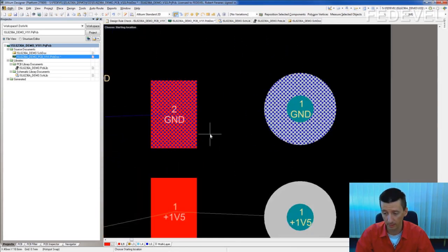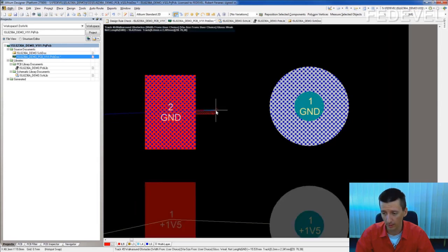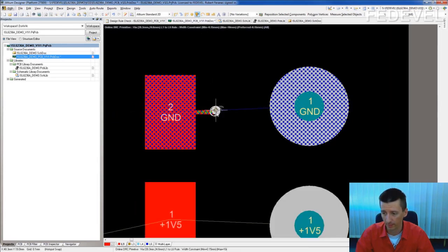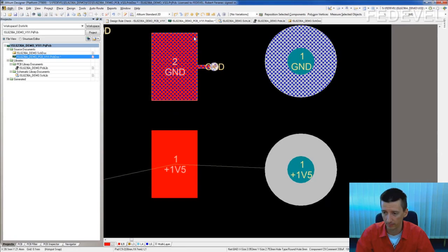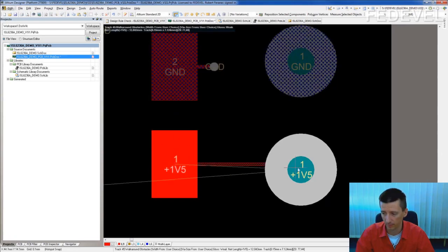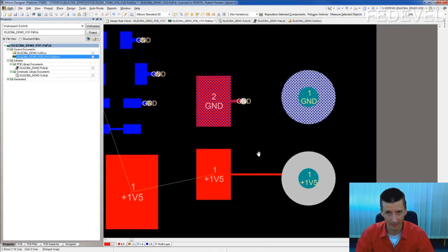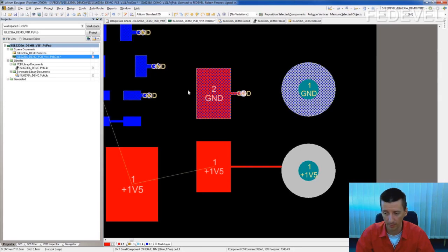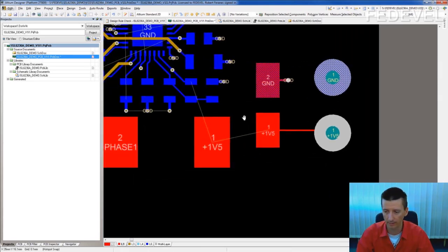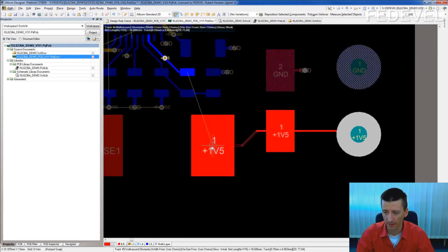And I will then explain what connections are important, and we will improve them together. Because some of these are not really how they should be. For example, big capacitors, they should have more vias. I will explain. Because there are big currents.